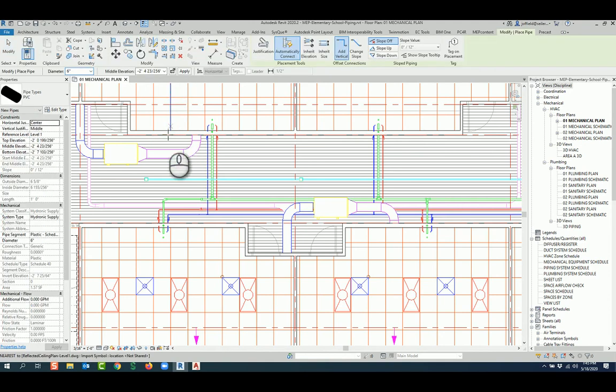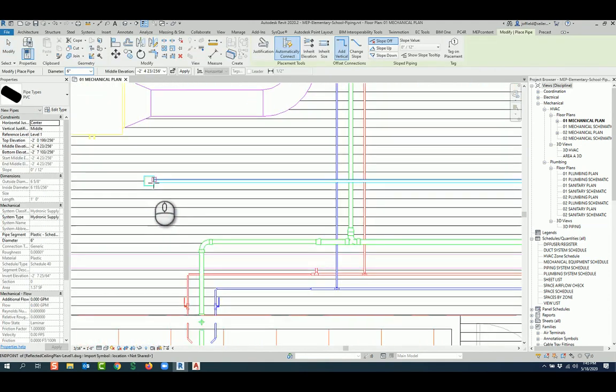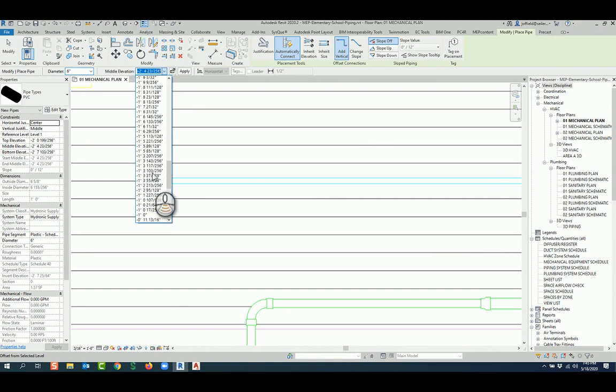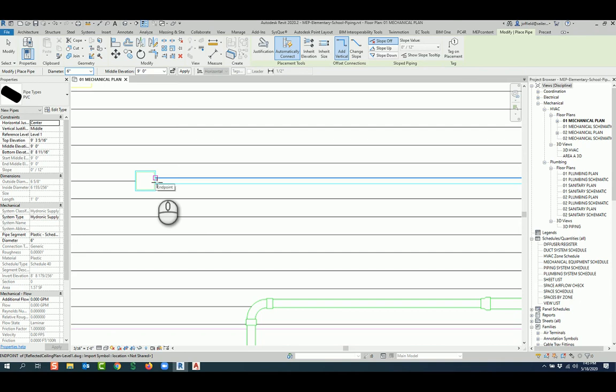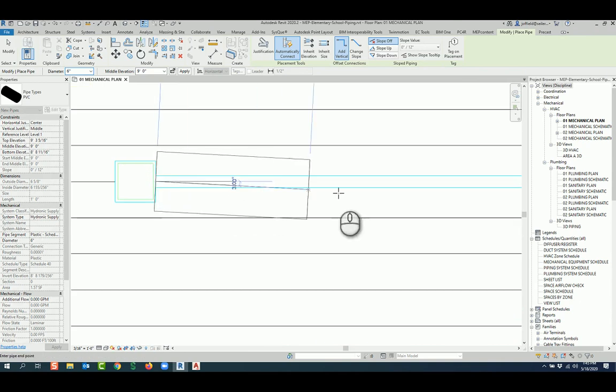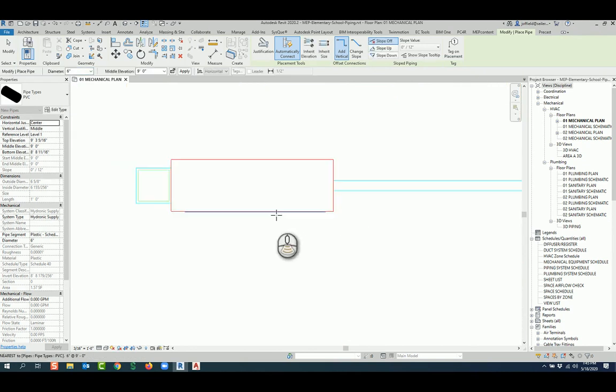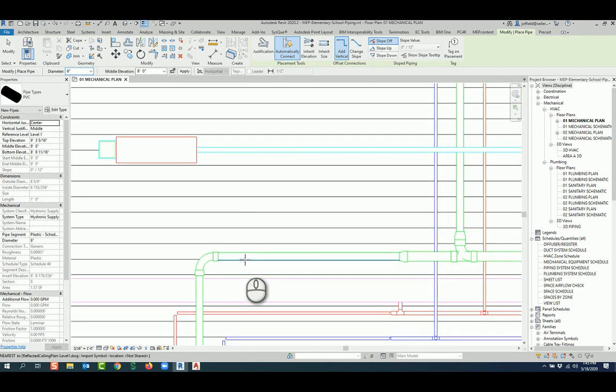Say we're doing some piping, I can go in and just start with my piping tool. Notice it is picking up the snap points even from a DWG file. Let's make sure our elevation is correct. So let's go up, find our correct elevation, and then here's our mid start point. Just because the justification we're picking is also from that middle point as well. And you can see how we're actually utilizing that particular center point. Now realize that that is conduit. We've got some piping down here.